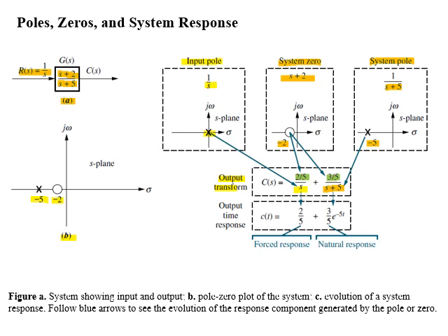Now if we look at time domain response, c(t) equals 2/5 + (3/5)e^(-5t). If you take inverse Laplace of (2/5)/s, we get 2/5, and this part was due to the input pole, so this will be our forced response of the system.